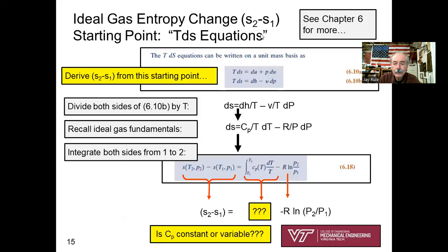Okay. So this is the entropy change starting point. My job, let's say in chapter 6, I'm asked over and over, calculate the entropy change S2 minus S1. And a lot of times that goes into needing to calculate entropy production sigma, but the first step is to calculate S2 minus S1. Many students have a tough time with this, and I'm trying to give you some starter tips on how to get started.